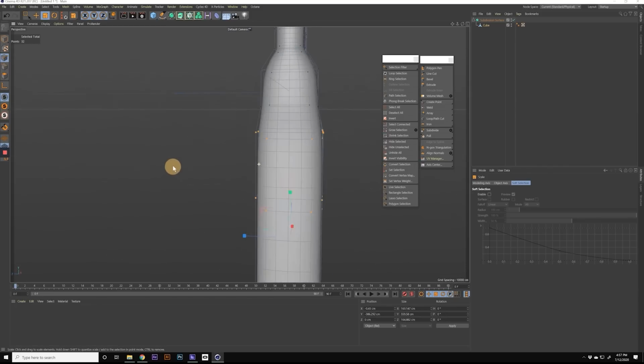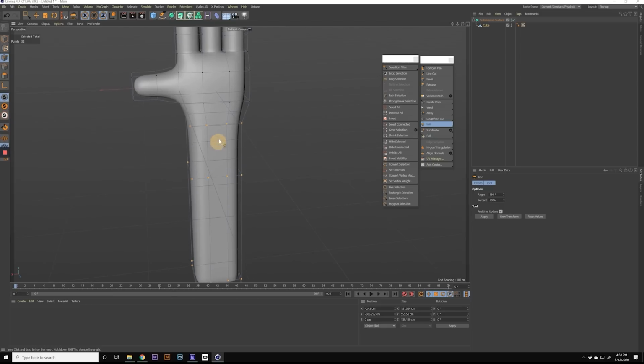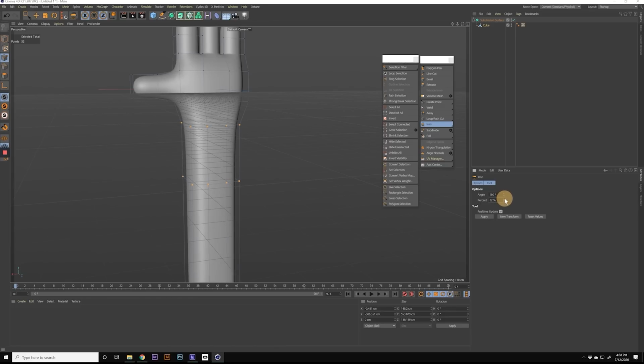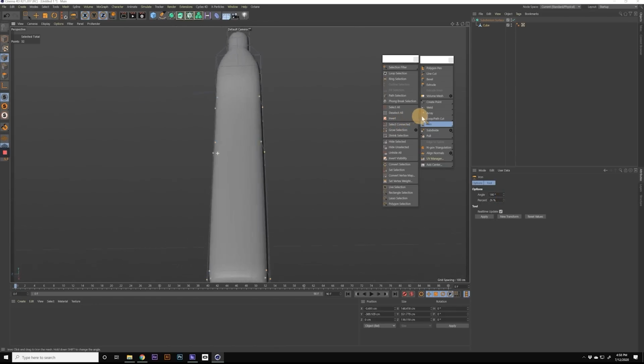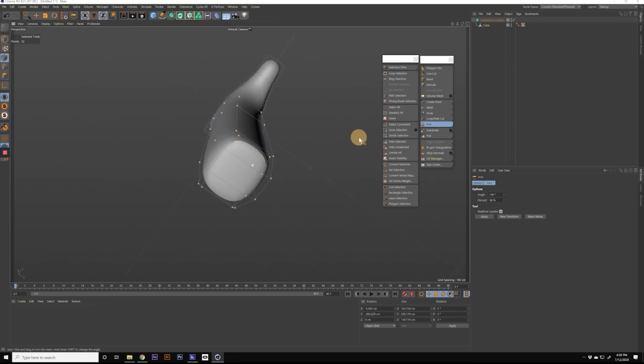So to make this a little bit more cylindrical, we're going to use the iron tool. So you can come over here to your iron tool, use the keyboard shortcut MG, and with our point selected, you can just kind of click and drag a little bit. And if you come over here to percentage, you can have some more granular control over that. You can just kind of do it to your liking, but basically what it's doing is pulling the points around to make it more circular.